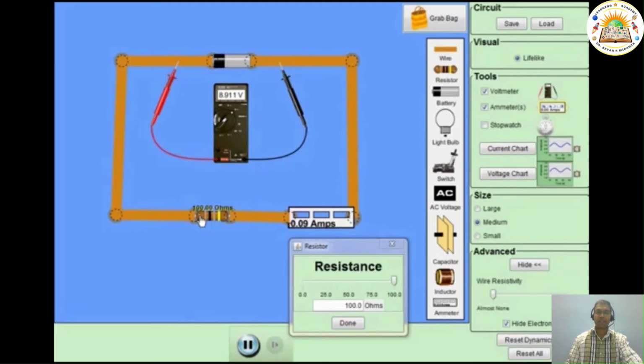So somewhere when I come to 60 volts, it's 8.7 and so on. It is decreasing. So you can see that the external resistance has decreased to 4.71 ohm. From 100 ohms, we've reduced it to 4.71 ohm. So roughly around 95 ohms of change, we have reduced it.